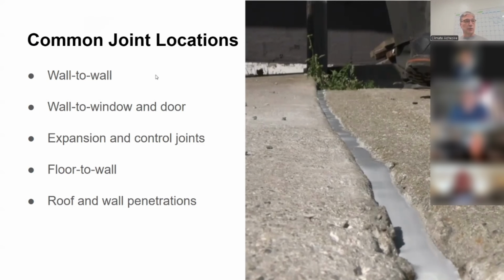If you're not familiar with masonry walls, if you have a masonry wall, every 20 feet on center, you need to put a half-inch vertical control joint in the wall to control movement within that wall. If you don't, you'll get cracking. And so the whole point of the control joint is to control that movement, and then we want to seal those joints to prevent water and moisture or moisture and air intrusion.